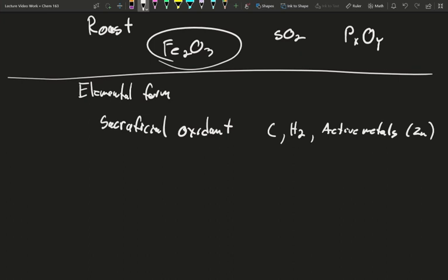In the old days it was coal that could be powdered and crushed up. When this is added, the oxygens will move off of an iron onto the carbon, and then the CO2 gas drifts away. And so as long as your system's set up correctly, you don't have an equilibrium reaction, the redox occurs, you end up with molten iron at the bottom, your CO2 and the like floats away out the air vents, and you can pour out and collect your molten iron.